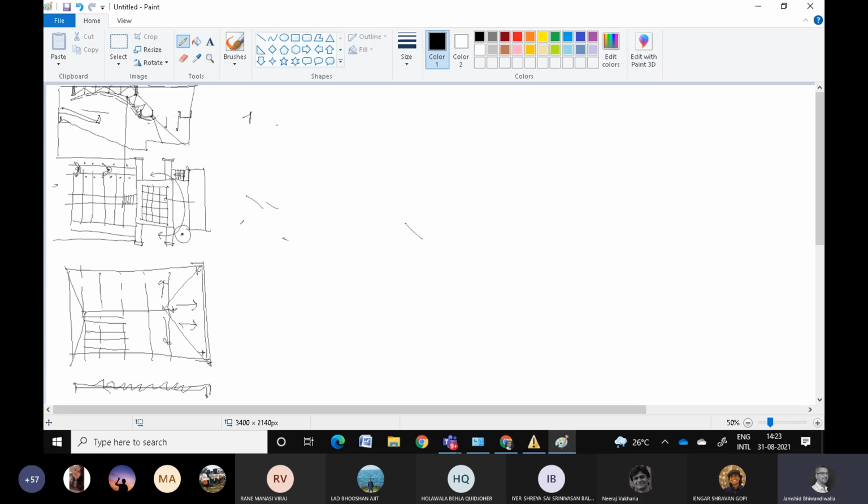You have smaller surfaces to drain off from one level to another. So you have a roof like that, and on top you have another, maybe skylighted, roof. This water slopes off and drops onto this, this water slopes off to that, and then it slopes off. So if you have a flat roof, break up your roof as far as possible.